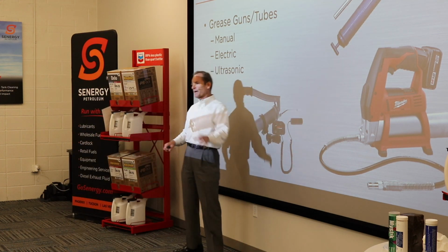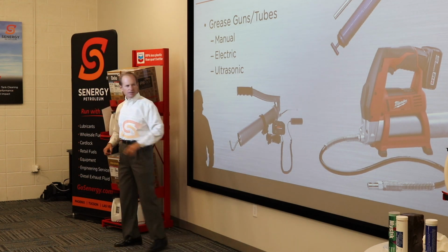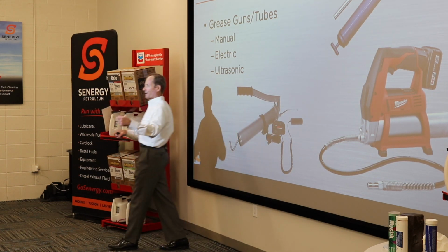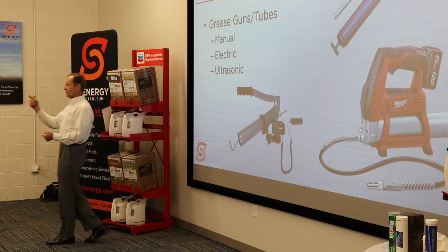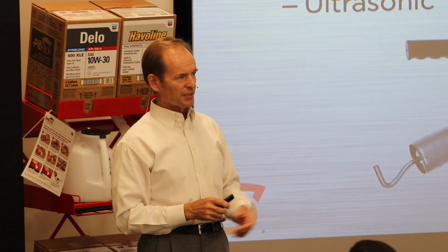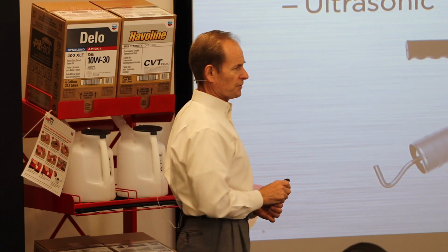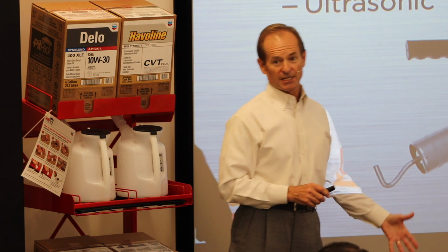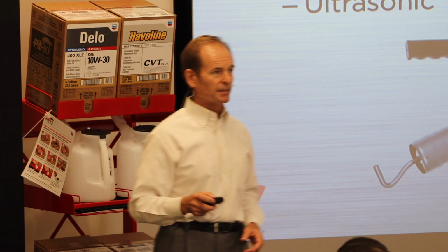You put that on your pillow block bearing, and you get a bar readout of how much noise is going on. You start pumping in the grease, and you can watch the noise level decrease as the grease is going into the bearing. So you know when to stop putting in grease when you get quiet enough. They also have versions of that with headsets, so you can hear what's going on as well.